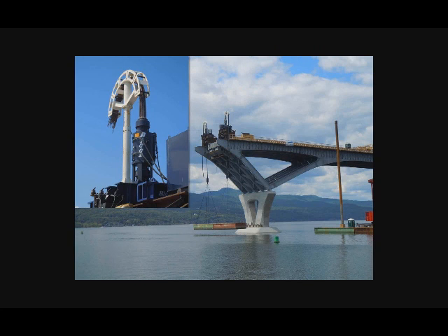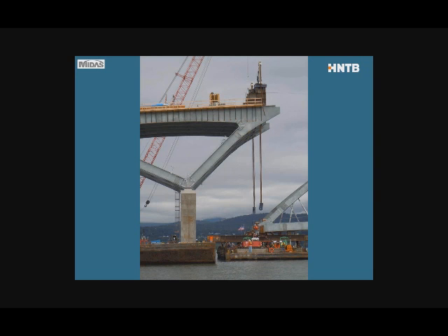So the way this works is it's a hydraulic jack that picks up, lifts 6 or 8 inches, resets the wedges, deflates the piston, resets the rear wedges, jacks up a little. This is how very heavy loads get lifted, and that white assembly is just to keep the strands from kinking, so just to deviate them. This is a tri lift, so this is just dead weight in the front.